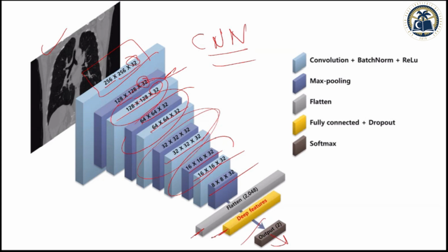If you're trying to design a CNN which could do almost near real-time processing and process hundreds and thousands of these X-rays, yes, you can do that. But then you say, no, I only want to process one X-ray in 1 minute, for example, and 1 minute is good enough. Then you say 500 megahertz, and how many clocks you have in 1 minute, so that will be your budget. You say, oh, I have so many billion clock cycles to do this CNN. So then there will be a very different approach.